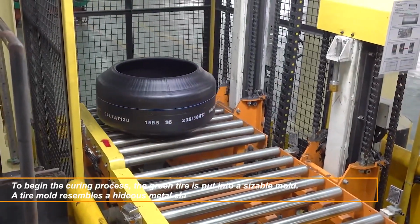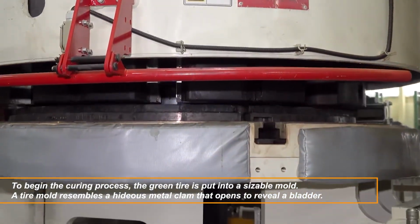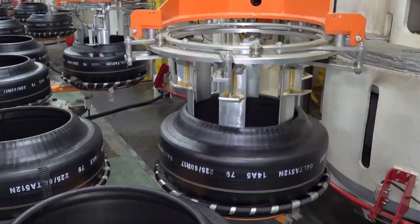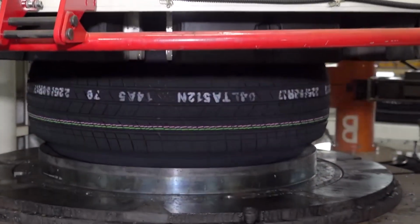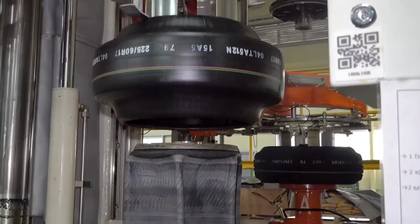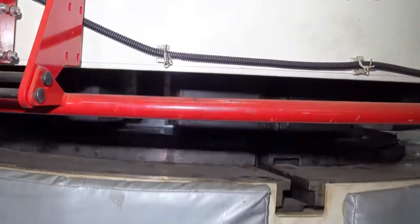To begin the curing process, the green tire is put in a sizable mold. A tire mold resembles a hideous metal clam that opens to reveal a bladder, which is a huge flexible balloon. After the green tire is positioned over the bladder, the clamshell mold shuts, causing the bladder to fill with steam and expand, forming the tire and pressing the raised interior of the mold against a blank tread rubber. The green tire is heated to 280 degrees by the steam during this curing procedure.